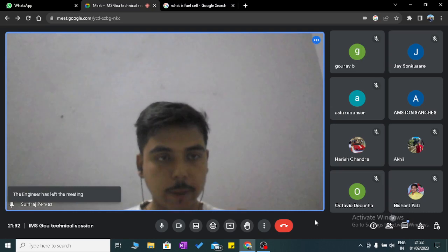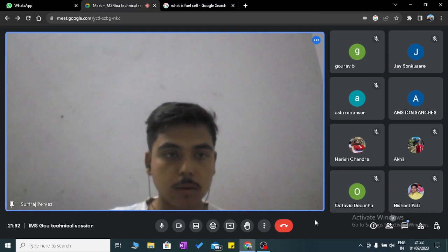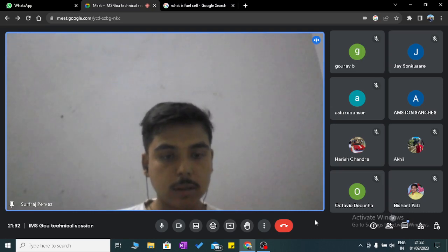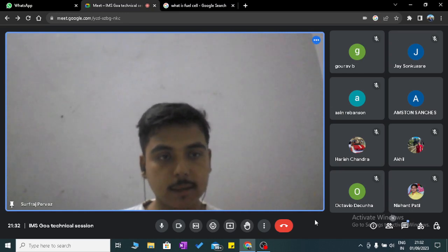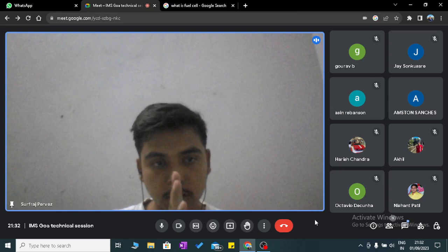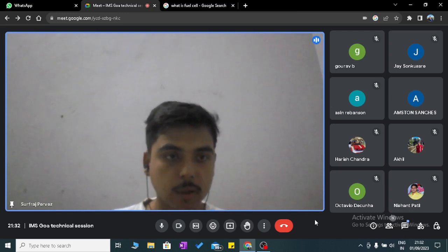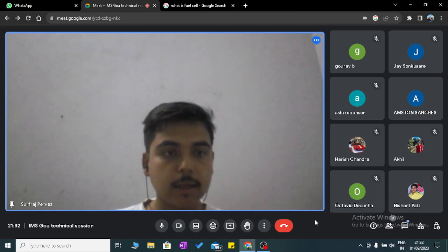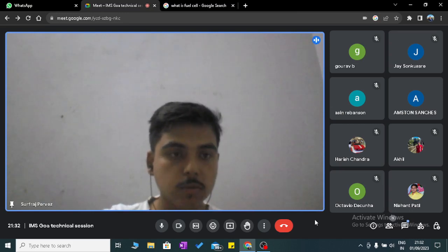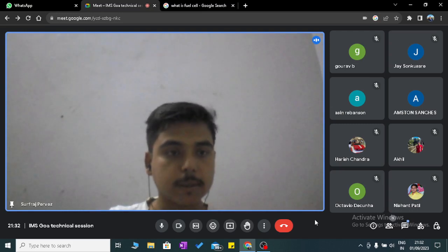If there is space in between, since four chucks are present at four different sides, suppose the chuck at the top, and towards that side the arm is not connected with the job. First we will loosen that top part, and then we will tighten the bottom chuck. Are you getting it? I'm not able to explain it properly, but are you getting it?